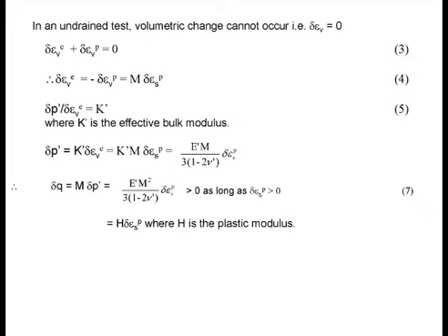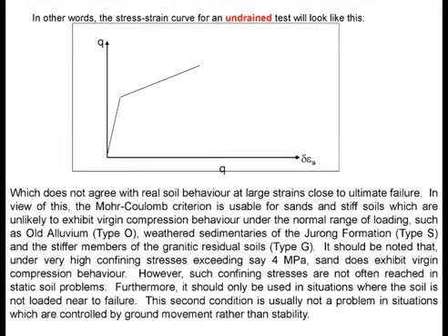Okay? So that is the disadvantage. And what it means is that in effect, the soil never fails, because you never reach a terminal strength. It just keeps going up. Okay? So this is essentially what is happening. And when you plot the stress strain, I don't know whether I plot it here, the stress strain curve will look like that. I think when you run your FEM, you will see the stress strain curve looking something like that.